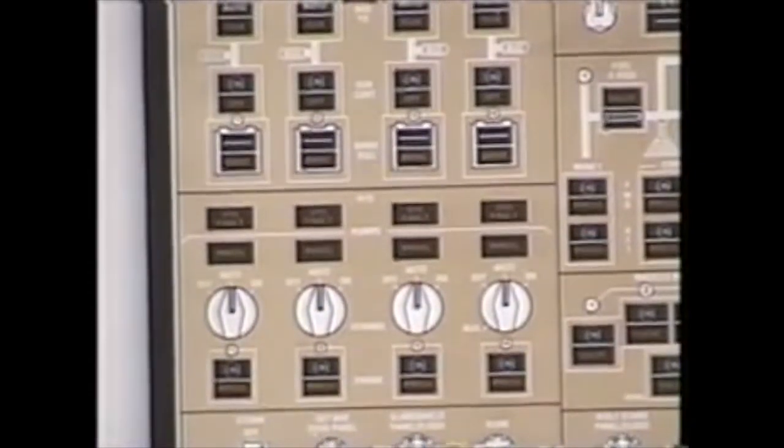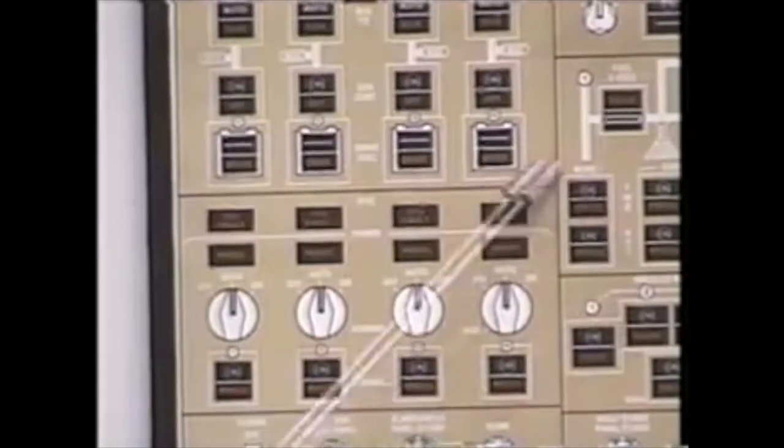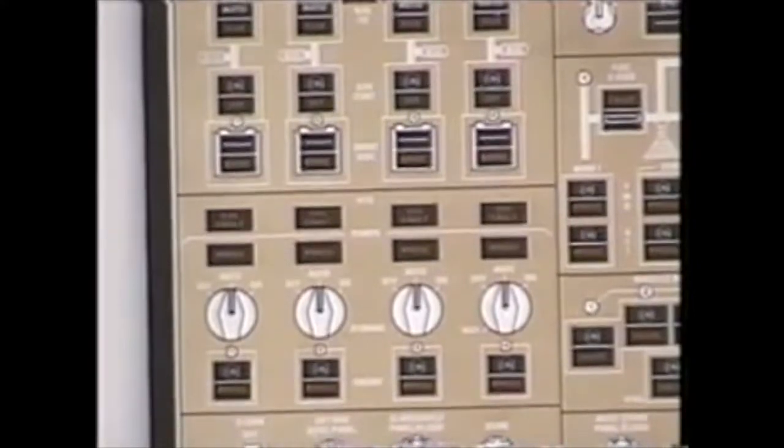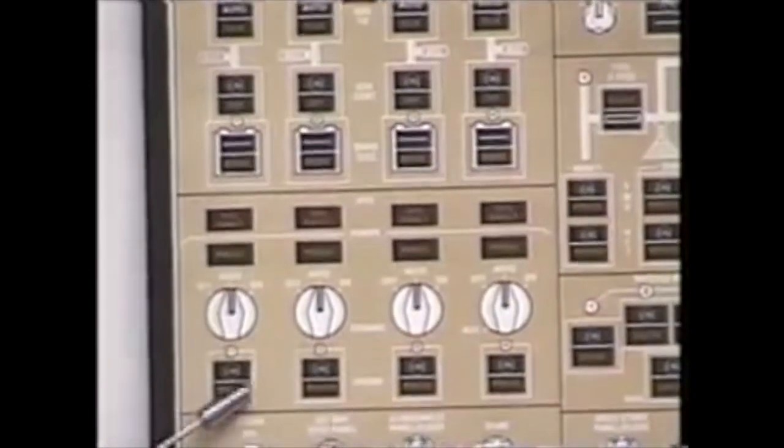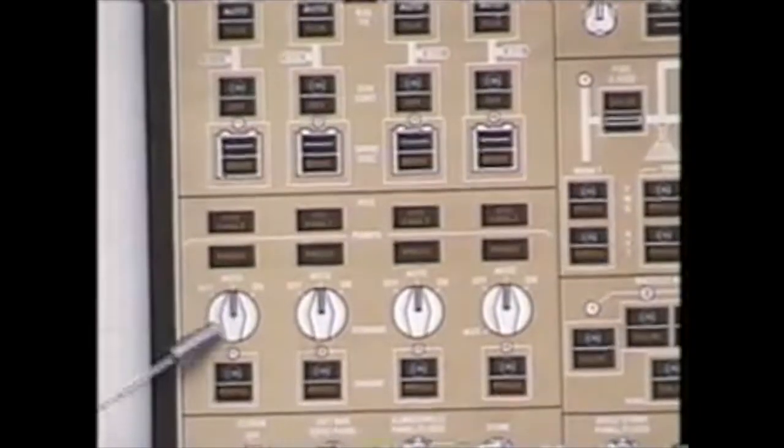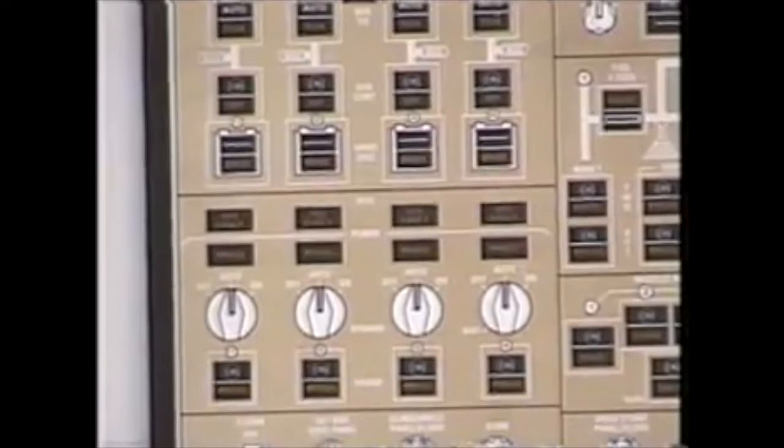Dropping down below the electrical panel is your hydraulic control panel. Hydraulic control panel, there are 4 separate, totally independent hydraulic systems, referred to as system 1, 2, 3, and 4. Each system has 2 pumps which can pressurize it, an air demand pump and an engine-driven pump. Air demand pumps, referred to as ADPs, and engine-driven pumps, referred to as EDPs. Air demand pumps take pneumatic air from your pneumatic system to operate. Air demand pumps are 3-position switches: off, auto, and on.